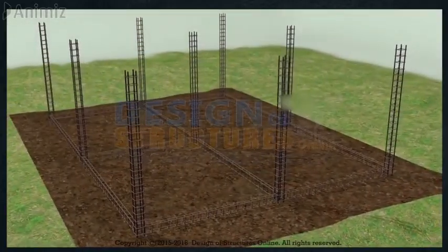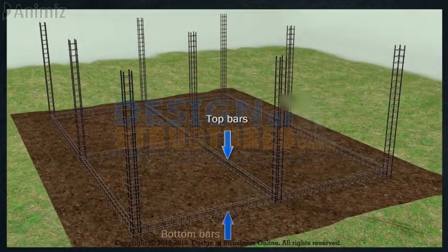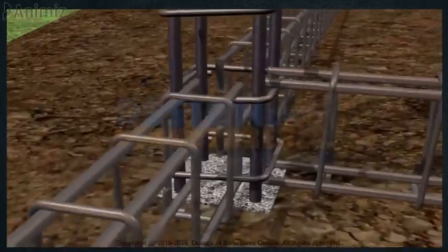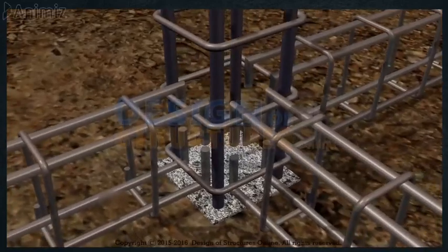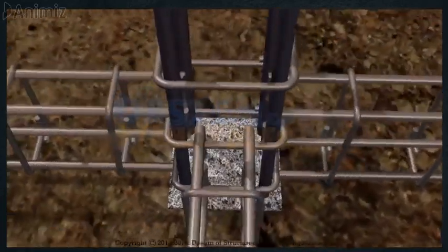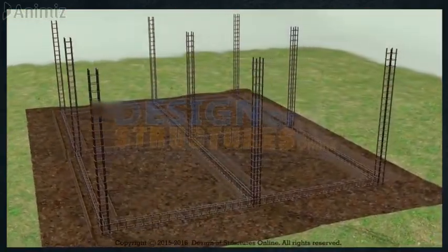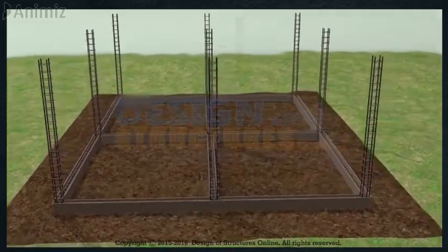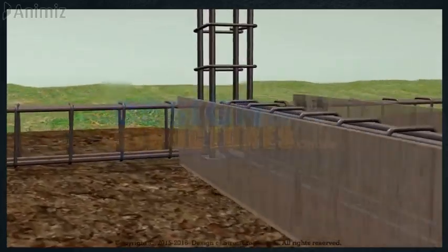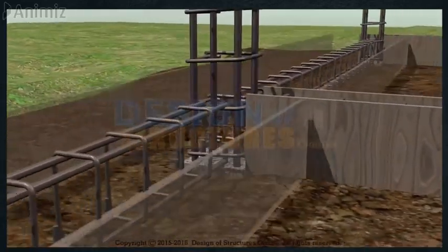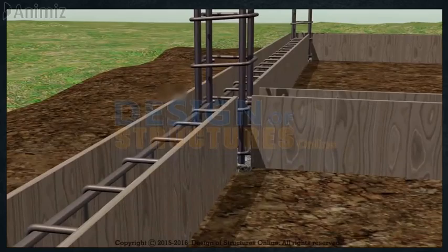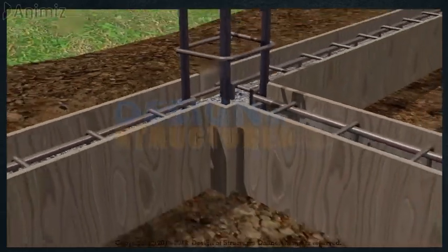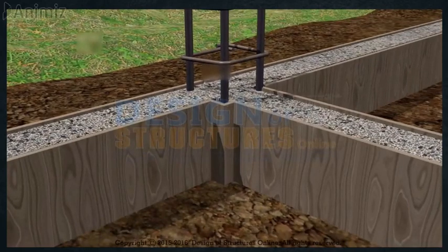Beam reinforcement shall be as per drawings. Top bars, bottom bars and stirrups to be placed with proper development length. Joints in the beam shuttering should be tight against leakage of cement grout. Construction of shuttering should permit removal of various parts in desired sequences without damage to the concrete. Beam concreting: the beam is poured with concrete of the grade mentioned in the drawings.